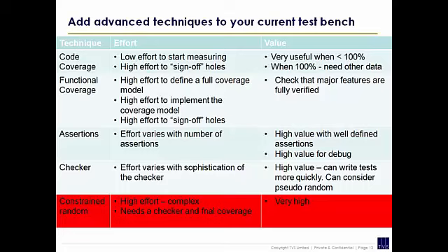It's reasonably high effort, but it allows you to check that all the major functions are fully verified. Okay, so when somebody writes a directed test, you can check that that directed test is doing what you expect it to for a functional coverage model.